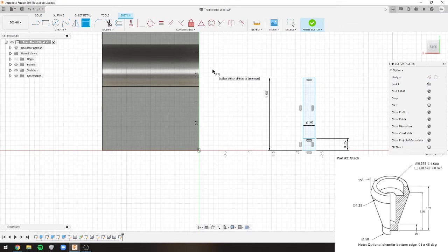So we're going to start from there, and then I'm also going to add this top part, which is going to be another little rectangle. I've got to go through and add a line that goes out here to here. I wanted this to be at the same height. I'm given the diameter of this top portion right here, the widest point up at the top, is supposed to be 1.25. So I'm just going to leave this about here because I'm going to select my dimension tool.